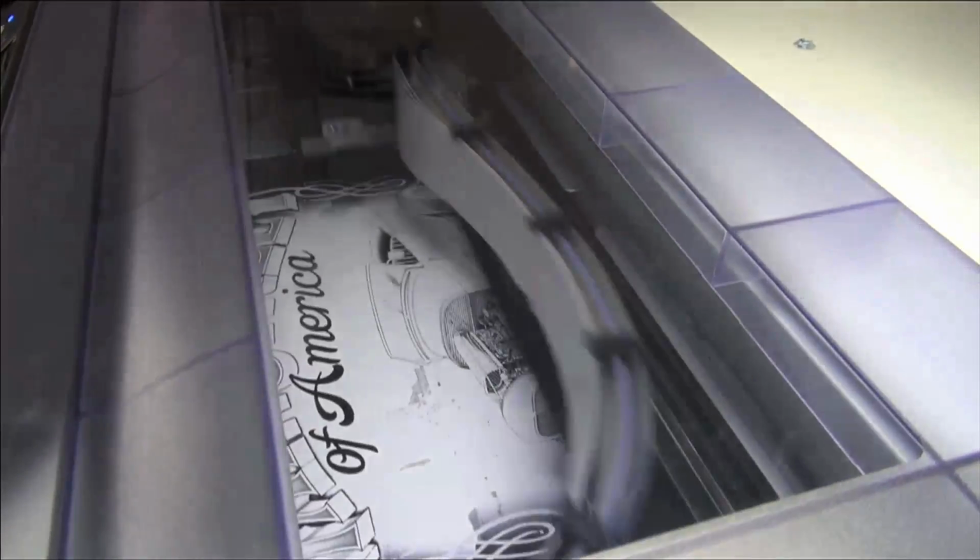Now, compared to screen printing, it really doesn't matter how many colors I have. That is the bonus of direct-to-garment printing. I can have 2 colors, I can have 20 colors. It can be photo quality, it can be gradients and fades and spatter and all types of different attributes to a design that really doesn't make a difference as far as the cost to produce and the time to produce.